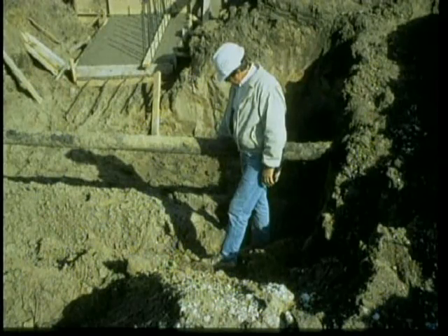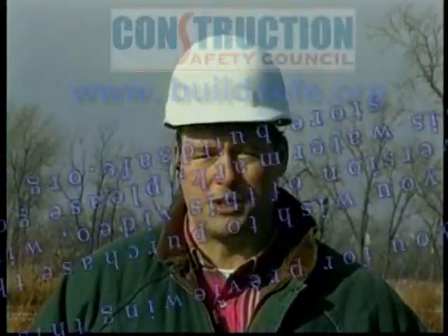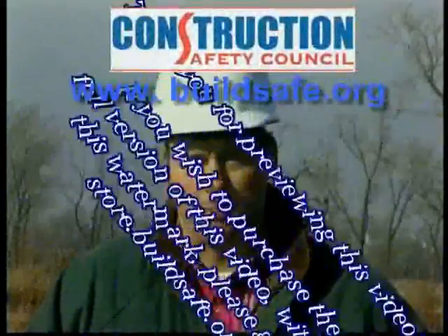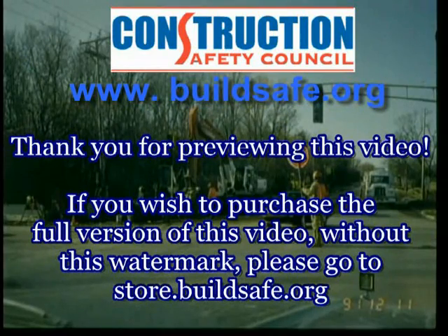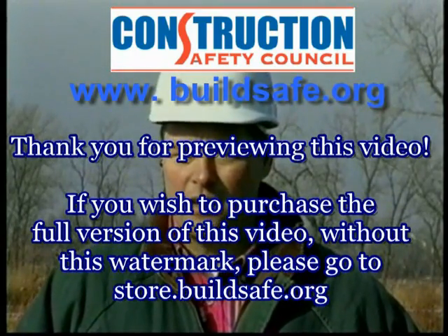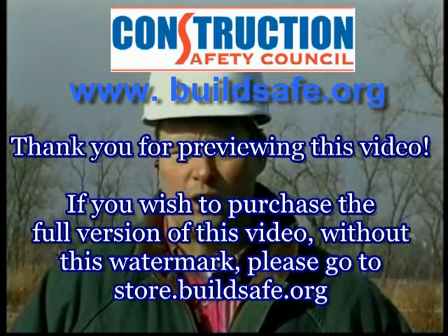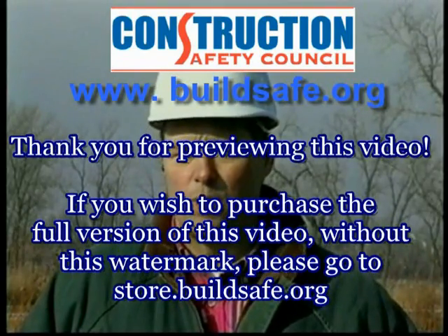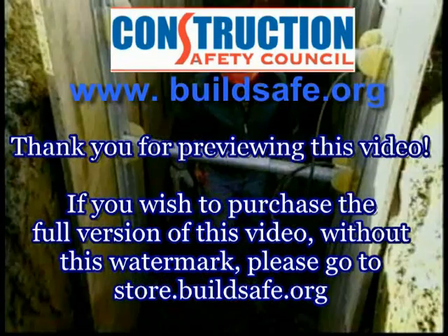As work goes on, inspections are required every day before work begins. Inspections are also required after rainstorms. If the excavation is subject to periods of heavy vibrations, such as from passing trains, pile driving, or heavy traffic, inspections of the excavation should be made frequently. And if there are conditions nearby that could produce hazardous atmospheres, the air in the excavation should be monitored throughout the day. Inspect for water daily.